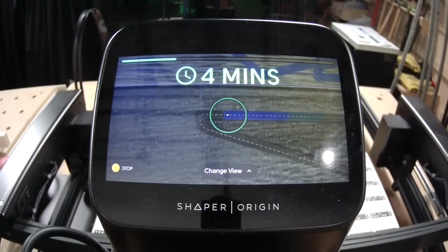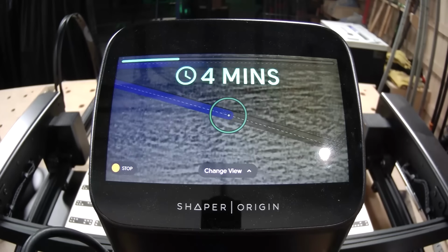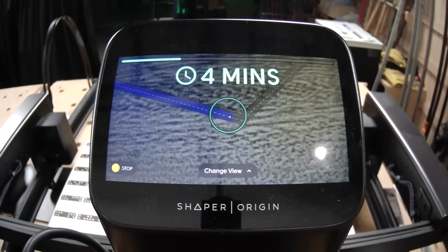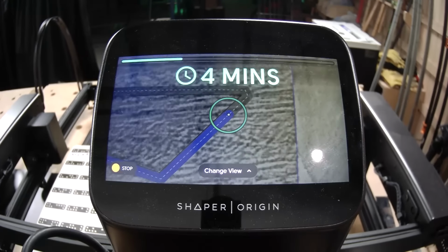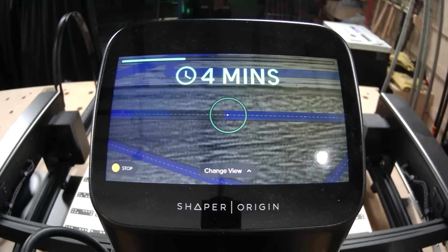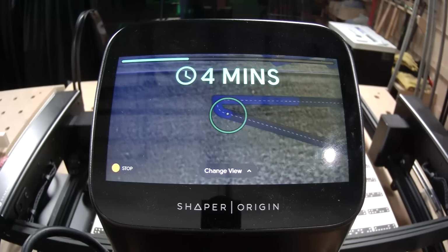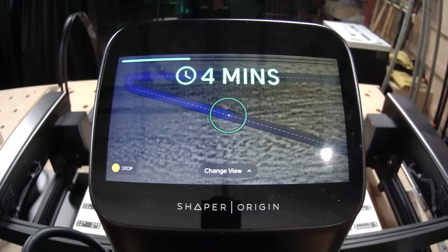Right. Would you want to also change the spindle speed for that, or just the feed? If you're running it really low, yeah, definitely up your spindle speed. With Bench Pilot, given that we're moving so fast these days, I keep that spindle at around a 5. Okay. For most bits, 8mm, quarter, 1/8 inch.